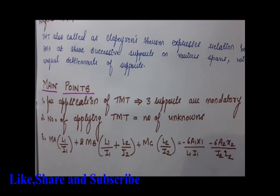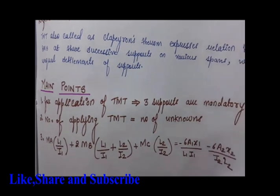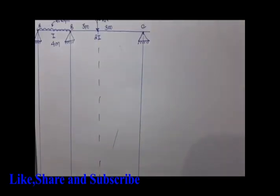If there are 2 supports on the beam, then TMT will not be applicable. Number of times of applying TMT, that means you are applying the TMT many times, will always be equal to the number of unknowns, and this is the formula. So let's get started with our first numerical.